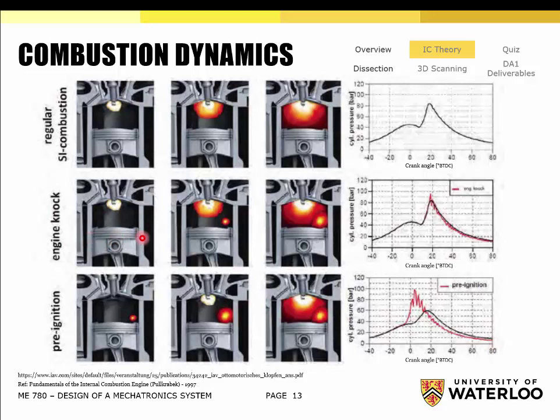This is when you've already ignited the mixture, but somewhere else there's a small other combustion event that's happening. It could be one, it could be many, it could be multiple events that are happening, okay? Something that's slightly different but not as common is what's called pre-ignition.